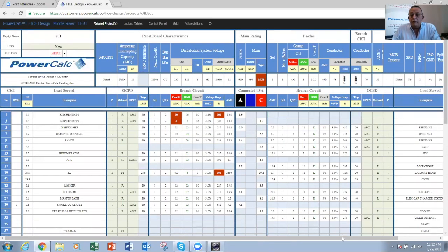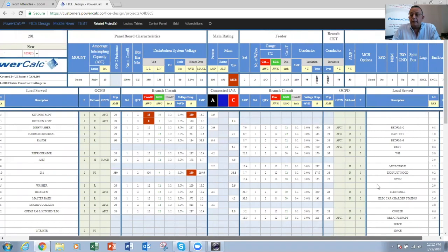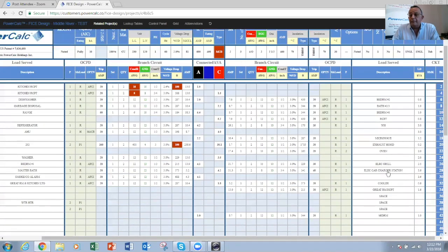If we go to circuit 42 on the right side of the panel, here it is, with my misspelled bedroom. Here's the load, 1 kVA. The number of poles is 1, and the load type is R. You see that the software calculated the circuit values for you in here. This is a 2, number 12 conductor with a number 12 ground, 1/2 inch conduit, and for a 3% voltage drop, you can travel 344 feet with this particular circuit.